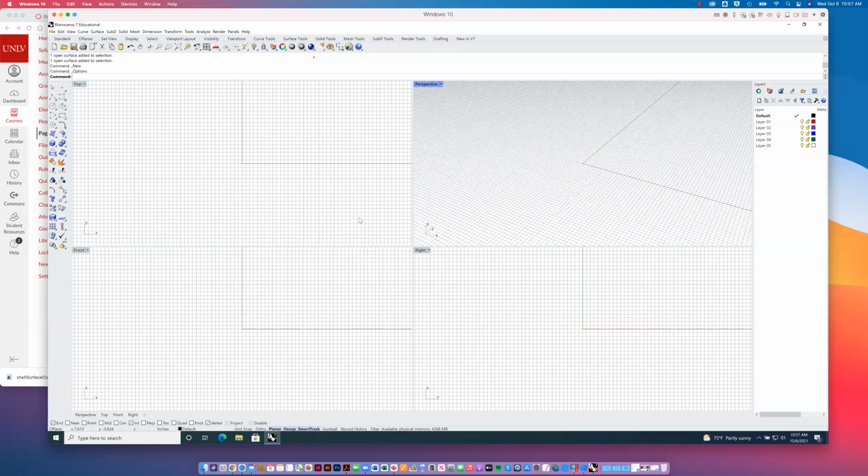If it's set to feet, you'll be off by a magnitude of 12 in scale, right? And if you're in millimeters, you'll be off by a magnitude of something ridiculous, like 25 or something, but in the reverse direction, you'll be way too small. So again, just make sure those units are set, okay?